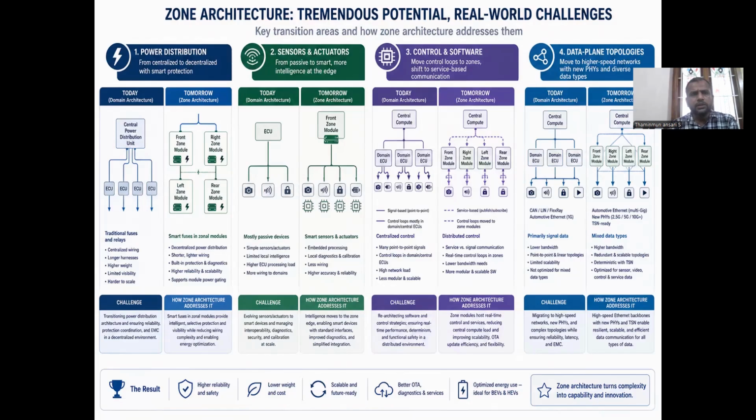In zone architecture, we are using something called a decentralized method with smart protection. Previously, we had a centralized power distribution method. We used to have a centralized power distribution unit, and from there every ECU would get its power. But in zonal, it is slightly different.